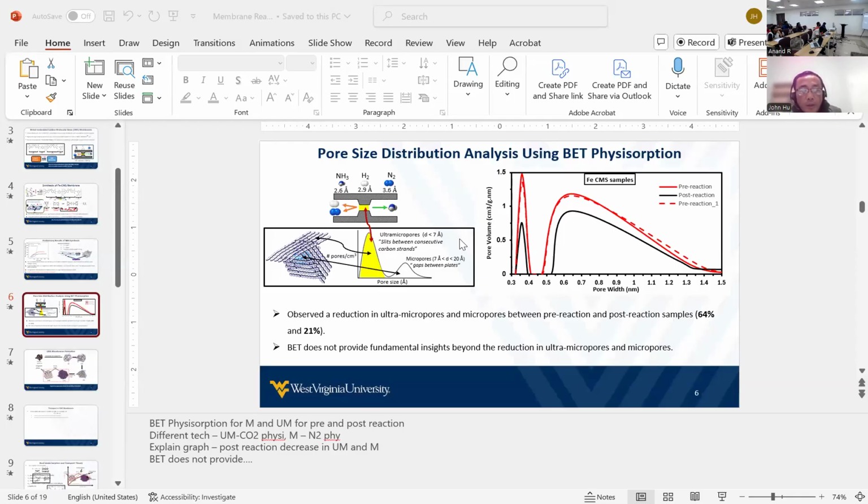So it's basically, even if I show it conceptually like this, you have a 2.9 angstrom opening that only allows the ammonia molecule to come in, leaving hydrogen and nitrogen on one side. The real membrane is actually more like fiber. Did you see this? More like, I would say, you call it a birdhouse, is that right? So basically you have a bundle of fibers, and you bundle them together, stack them together, and then the opening when the molecule goes through is like 2.9. So that's how they build the so-called CMS membrane.